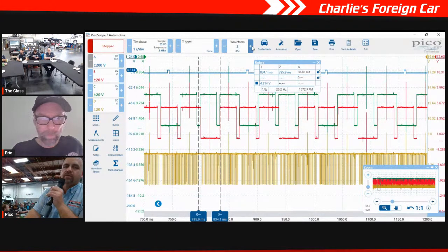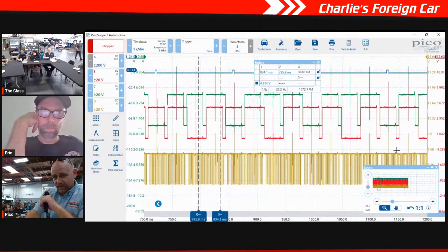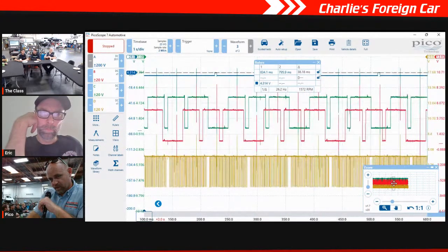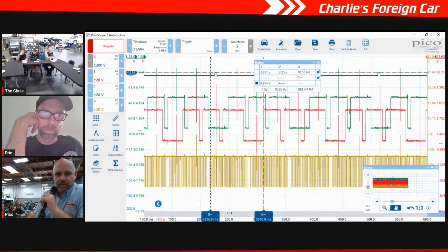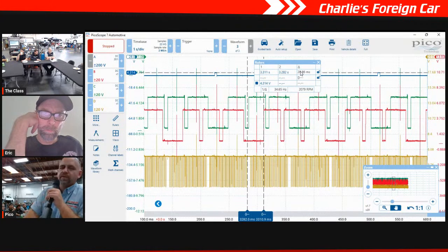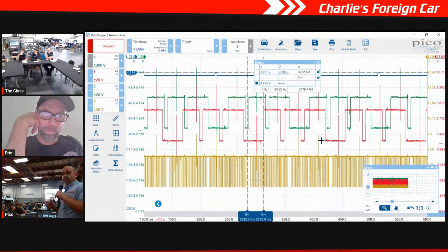So here, we're just going to go to waveform 2. That's a little bit different number, but we're going to try it here. So then on waveform 3, I'm just dragging this zoom bar over here. Somewhere down here, we know it was activated. We'll go to that same number right there and go to this same number right here, the leading edge right here. And that was at 28. So it's 28 milliseconds of time between the crankshaft and the intake shaft when it was activated.